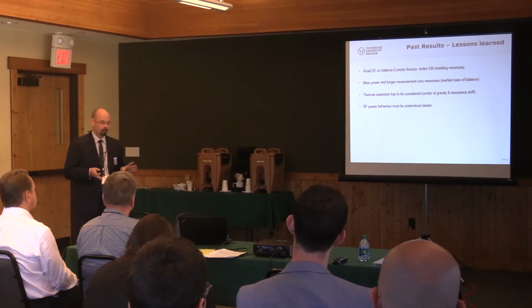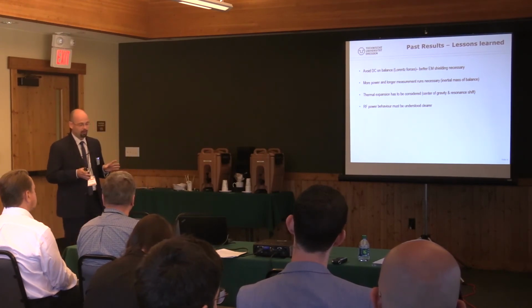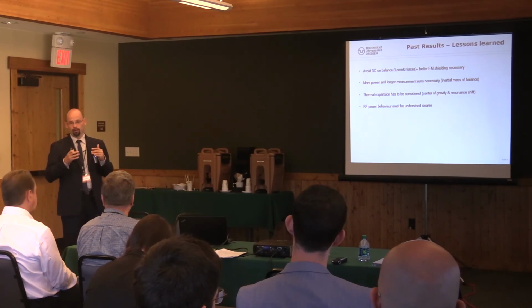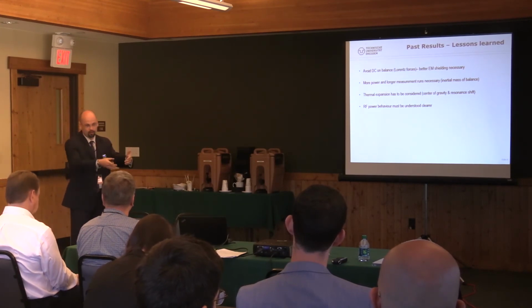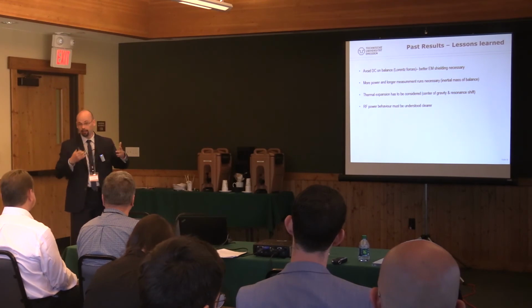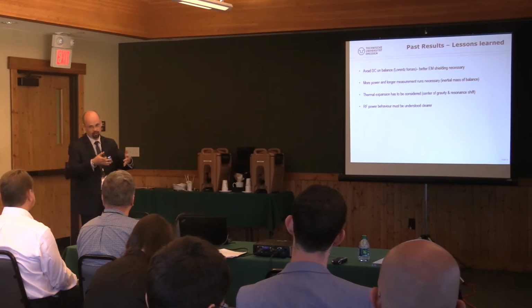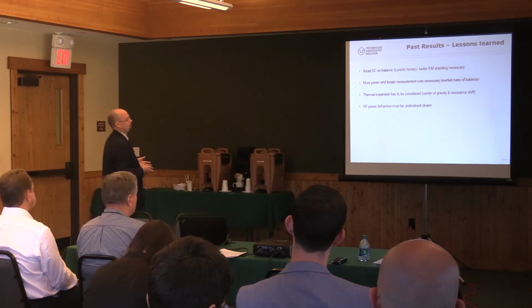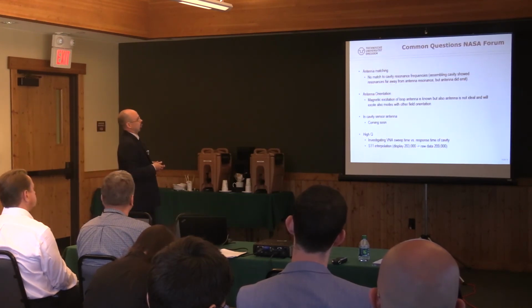For example, there were some measurements, some power spectra, where the reflected power, power which was reflected from the cavity back to the system, was even higher than the power we got into the cavity, measured by power meters at a bidirectional coupler. I'll come to that later.